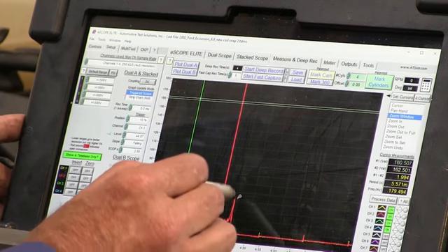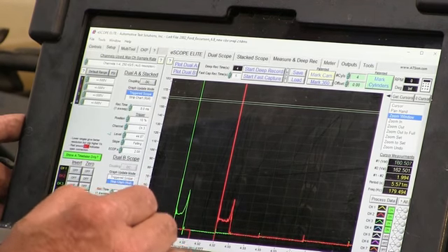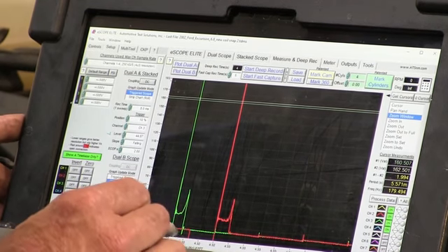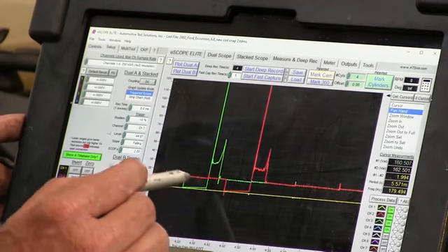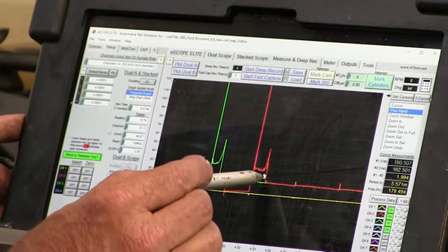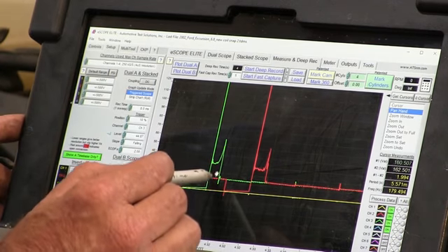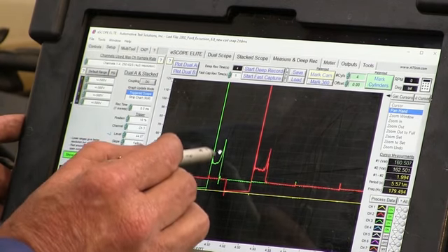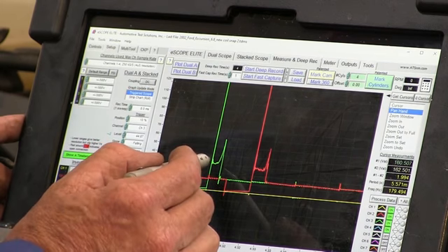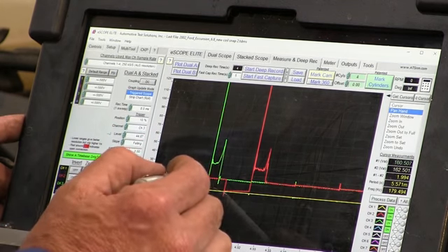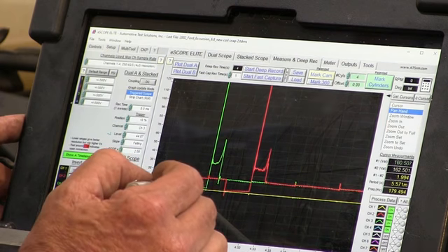Here we can see both of them giving a kick up, like a little lean kick here, and we've got a little bit of tail on 9, harder discharge. See how I have a bigger tail than on 1, so lean. 9 is a little leaner, and this probably is the leanest one because that's the one that carbon traced. But we're going to need to do something to clean these injectors before we return this car to the customer.